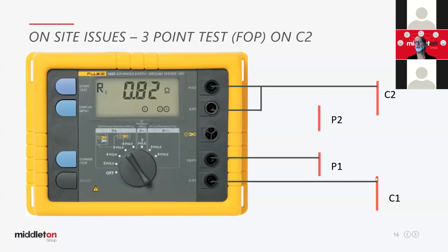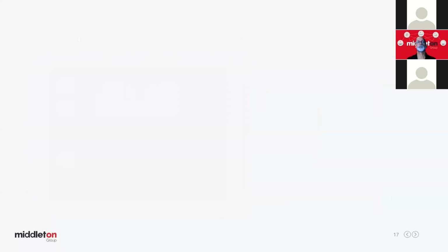You might find one that's relatively high, to go and work on that one, get it lower, remeasure it. Or indeed, even a balance. A lot of these meters like a balance from one side to the other to be similar in the impedances that they're seeing on each side from each terminal. This is a pretty handy method to know. You mightn't use it often, but when Murphy's around, that's a good one to cure the problem.